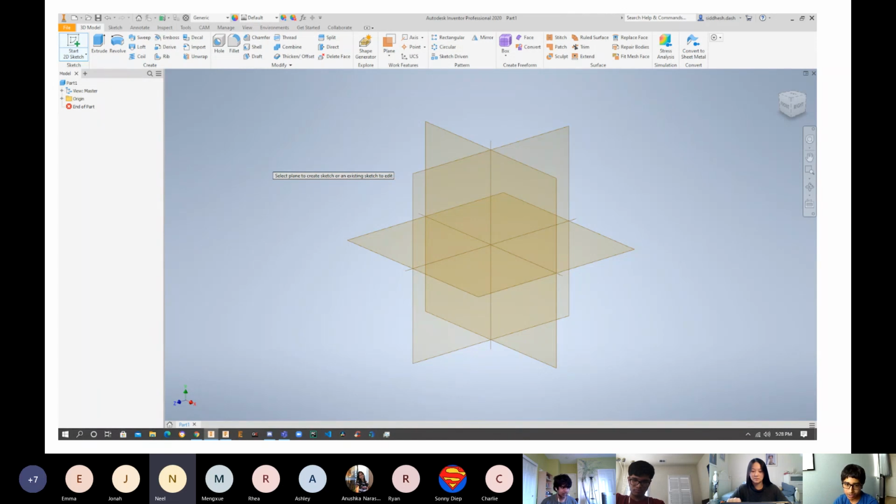So if you make a part off of your XY sketch and it ends up being oriented a different way, you're going to have to rotate that part in your assembly. And that means that every time you want to place a new part or a new version of that part, you are also going to have to do the exact same thing. Backwards compatibility gets incredibly hard with versions of the same part over and over again, right?